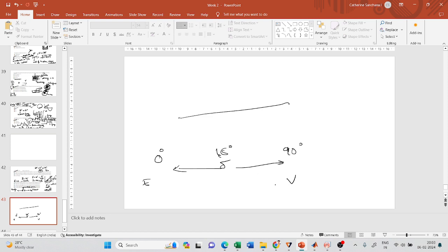So here, at more than 45 degrees, my G double prime will be more than G prime because the viscous component will dominate. Only when it nears 90 degrees will it be entirely viscous, right? Here, my G prime will be greater than G double prime because my elastic component will dominate. Only when it nears 0 degrees will it be entirely elastic.